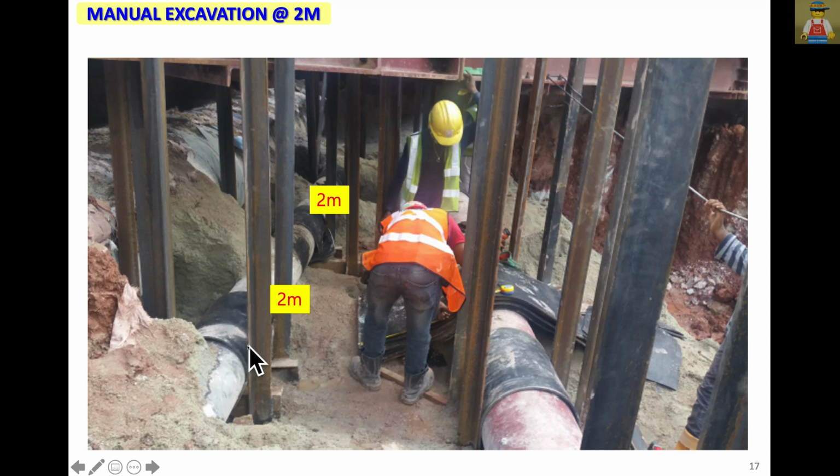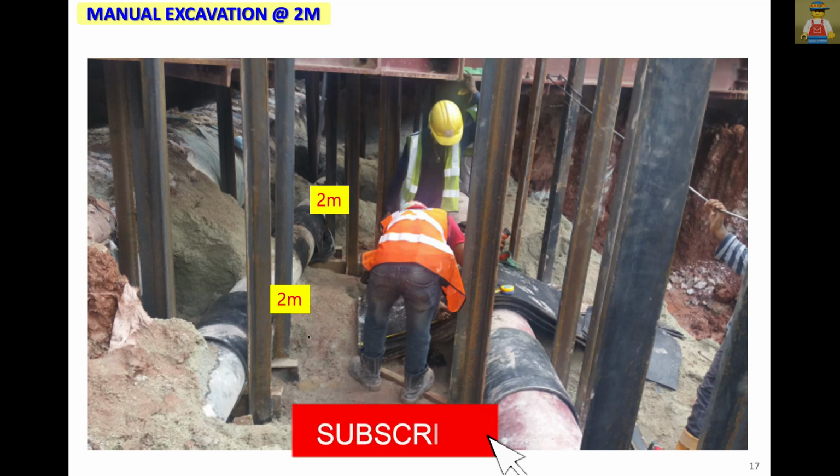Then why we use this rubber is to protect and to absorb vibration of the water pipe. The water pipe has high pressure inside, and above, if there is decking, the carriageway, while traffic is running, there is vibration. So this vibration causes damage on the connection between the strut, between the angle and the water pipe. So yeah, using the rubber to absorb some vibration here. If there is no rubber, continuous movement may cause some loosening or weakening of the welding. If there is a bolt, it will screw out. So this kind of detail I'll show you in each utility support method next.